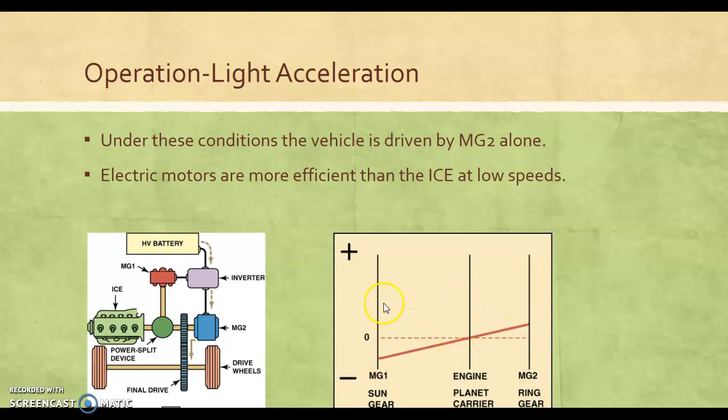And then the gap, the distance, you notice this is larger than this one. This is represented by the teeth. So we talked about that torque split that is fixed based on the teeth and gear ratio. That's the gap between these lines. So what the nomograph shows is, if this straight line is here, it tells me the RPM, positive and negative, of these three components in relation to each other.